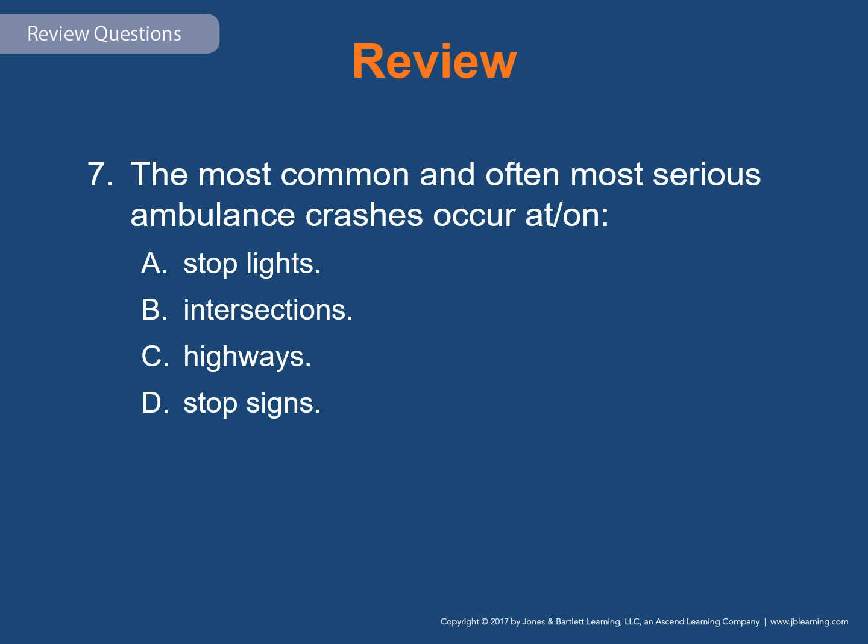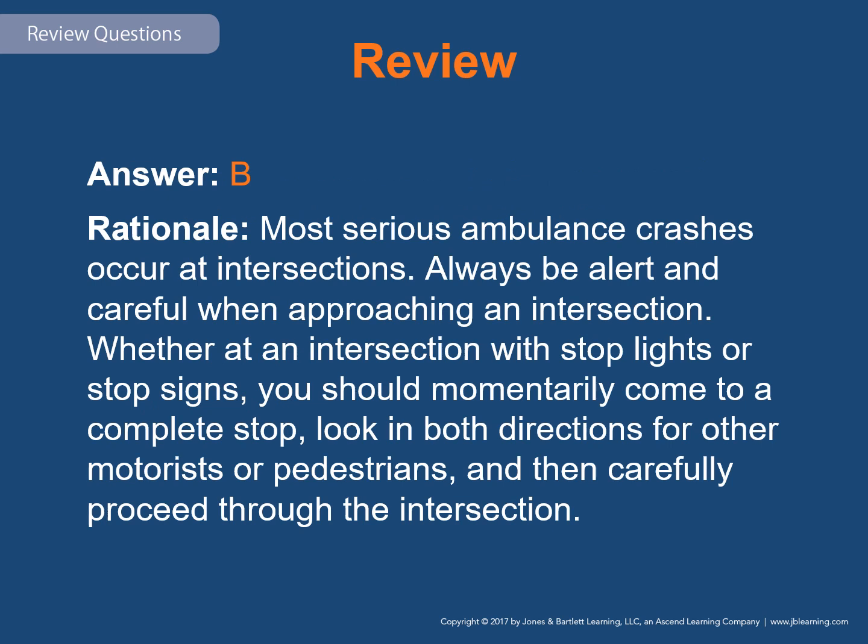Number 7, the most common and often serious ambulance crashes occur on or at A, stoplights, B, intersections, C, highways, or D, stop signs. This one should be absolutely easy. It is B. Most ambulance crashes occur at intersections. Always be alert and careful when approaching an intersection. Whether at an intersection with stoplights or stop signs, you should momentarily come to a complete stop, look in both directions for other motorists or pedestrians, and then carefully proceed through the intersection.